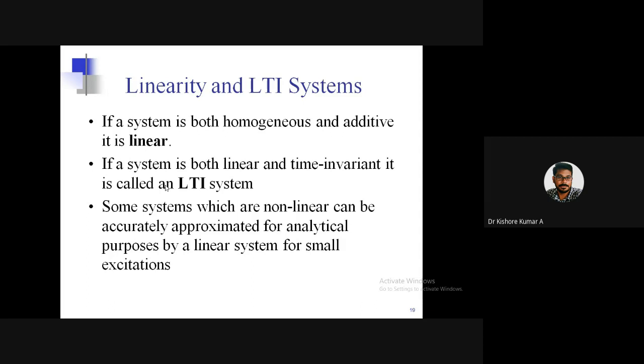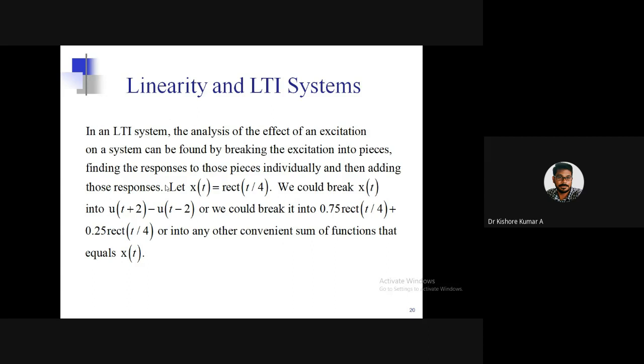Some systems which are non-linear can be accurately approximated for analytical purposes by means of a linear system for small excitations. Now, to depict the concept of linearity as well as linear time invariant systems, consider any LTI system. The effect of an excitation applied to the system can be found by breaking the excitation into pieces, finding the responses to those pieces individually, and then adding those responses.